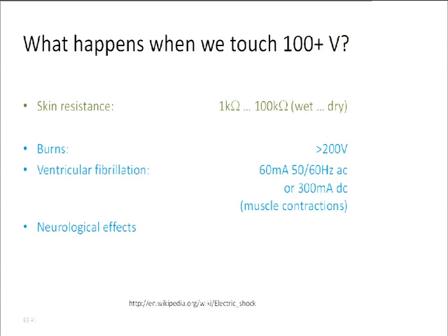So burns. So the first thing that protects us is that yes, our skin isn't a conductor. In fact, if our skin is dry, then the resistance through our body over any reasonable stretch of skin is on the order of kiloohms, but actually on the order of hundreds of kiloohms, okay?